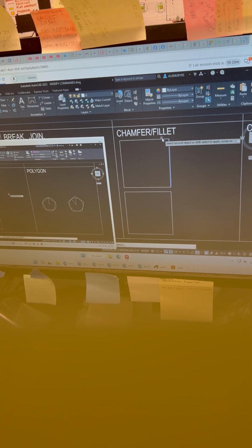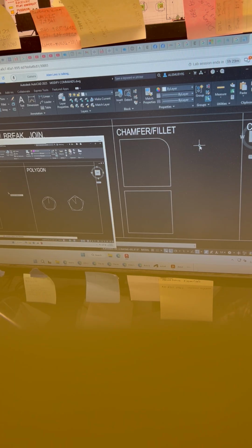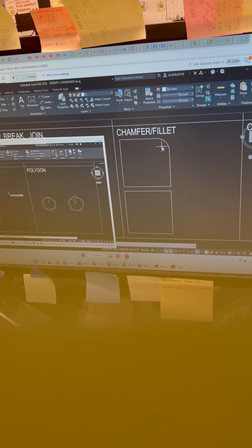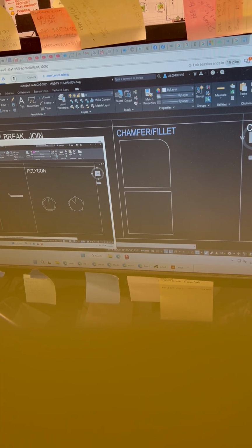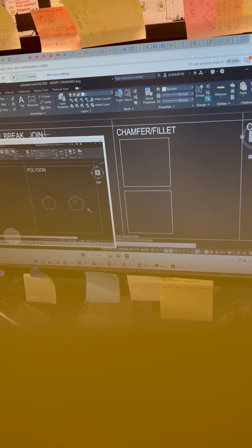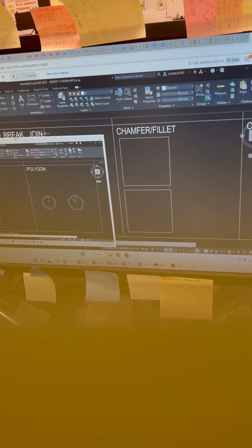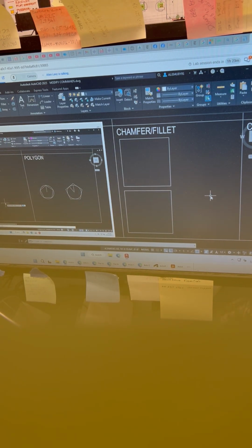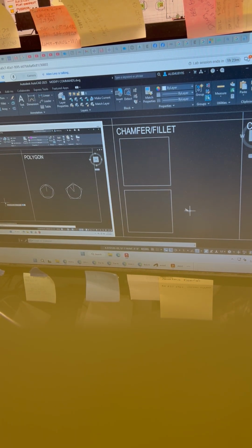Now, the first thing you might want to do is check to see what the radius is. So we want to create a little round, and we have to define the radius of that round. So one of the options being radius. Go ahead and start that option. It has a radius set here in this drawing of 1 foot. That'll be fine. We'll go with 1 foot. So I want you to accept the default. Just hit enter.